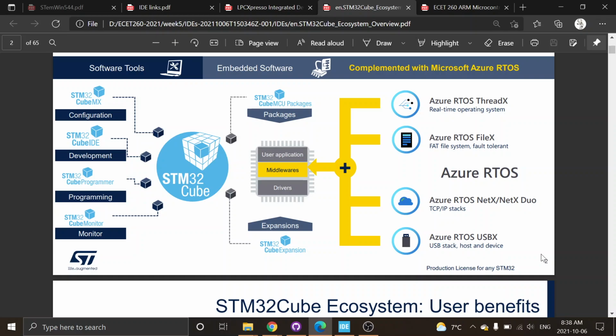And one of the things in one of the tabs of CubeMX is it says, what's your target? And there's different targets. We can do it for a compiler development environment called Keil, Atollic, which ST bought and put into the STM32 Cube IDE. That's MX and Atollic all in one. Before it was really working well, what we would do is fire up CubeMX, then open up Atollic and import your project that it generated and then compile it with that.